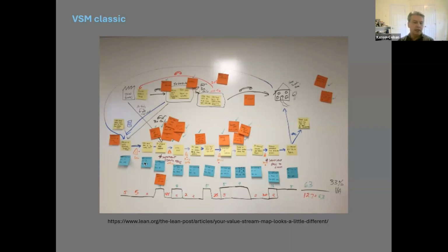This is facilitated by standardized symbols and key performance indicators that qualify individual processes, such as cycle time, delivery time, or lead time. Based on this evaluation, process steps contain non-value-added elements, value-added elements, and waste. You can identify the waste. The ultimate goal is to eliminate these by streamlining the production process, enhancing overall productivity.